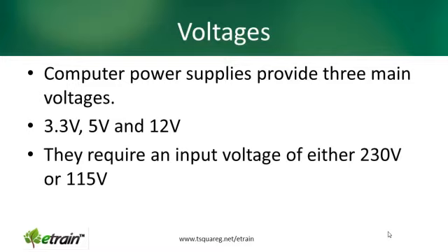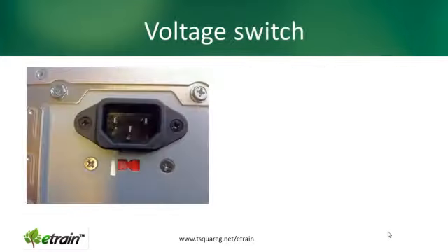To get it, we need an input voltage of 230 to 115 volts, or actually anything in between, but certainly not going too much beyond those two extremes. Now, to accommodate that, a lot of modern power supplies are auto switching. So you supply the mains current, it detects that voltage as well, and adjusts itself accordingly.